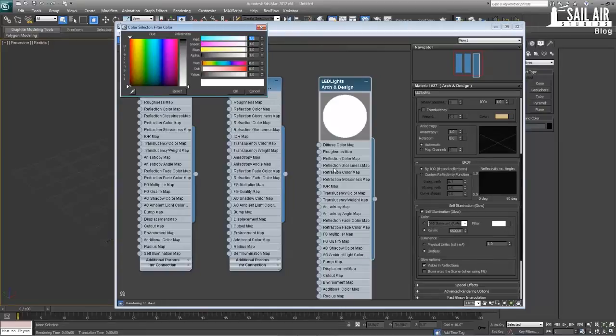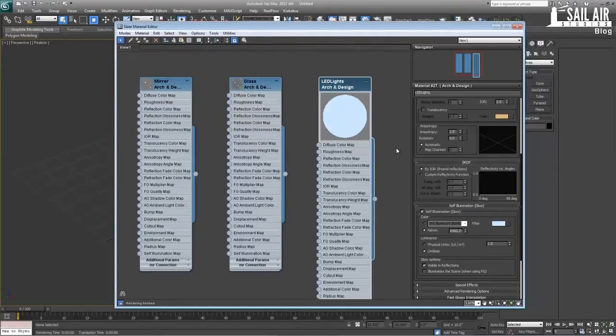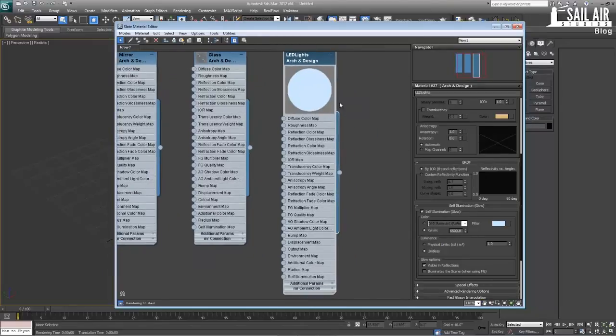And for our filter, we are going to use a blue filter, which will be, that's not where I'm going to put it in. 0.577 on the hue and 0.408 on the saturation. So just a very light blue filter with the value of 1. And that is everything we need for that.